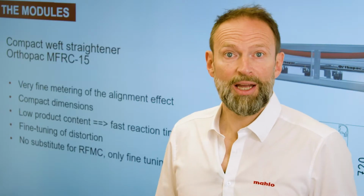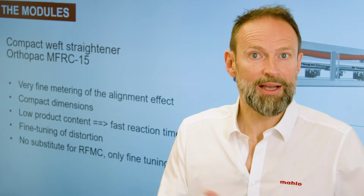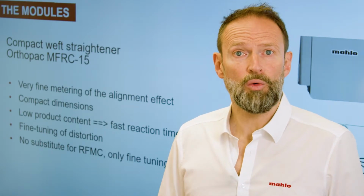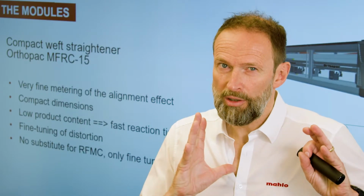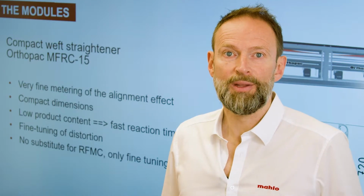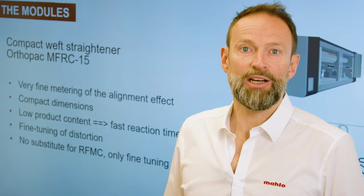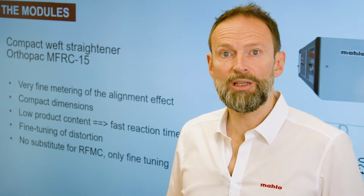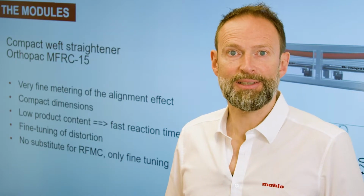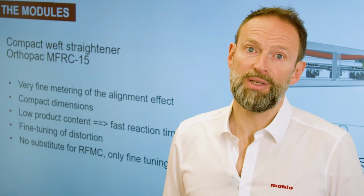You have to make sure that during the previous process, like the drying after bleaching or drying after scouring, you already have a fabric which is distortion free to 85-90%, simply because during the pulling at the entry of the printing machine, a lot of distortion might add on to that, and for that potential this small unit might not be sufficient.